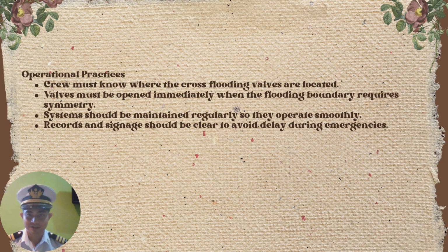Operational practice. Crew must know where the cross-flooding valves are located. Valves must be opened immediately when the flooding boundary requires symmetry. Systems should be maintained regularly so they operate smoothly. Records and signs should be clear to avoid delay during emergency.